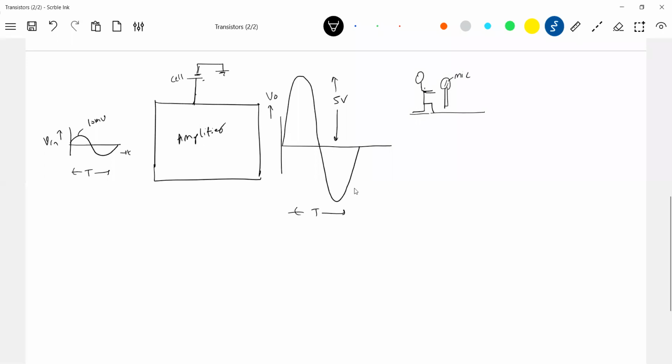He will speak, so the sound wave will come and strike the mic. There the mechanical sound wave makes the layers undergo displacement. Due to the change in resistance, an electric signal will be generated. That electric signal will be given to the amplifier.